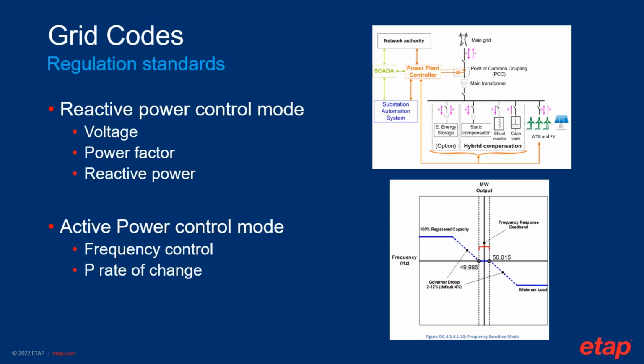The active power control can be performed centrally from the power plant controller, but the generation units such as inverter and wind turbine generator may embed active power control for under and over frequency conditions. In such a case, the renewable power plants have to manage an active power reserve for under frequency conditions and reduce the generated active power for over frequency conditions.